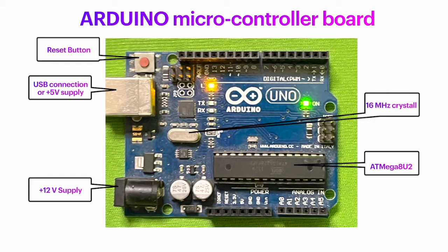One of the interesting things is that it also provides a 3-volt and 5-volt power supply. Though not much current can be drawn from this, it is usually enough for a small circuit to operate. It has a 3.3 volt supply, which is very popular among the various robotics interfaces or sensors. It also supplies 5 volts, and it has various grounds. You can see many grounds which can be connected in order to operate the external circuit for this